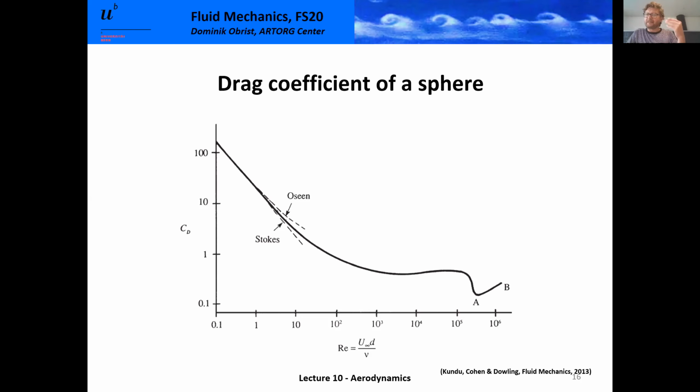One theory is that these dimples disturb the laminar boundary layer and trip it to make it turbulent. So the Reynolds number of a golf ball is not quite high enough to go through the drag crisis by itself. They added the dimples, and the little dimples make the boundary layer trip earlier, at a lower Reynolds number, so you can go through the drag crisis, with the result that you have a lower drag on a golf ball, and the golf player can hit the ball much farther than without dimples.